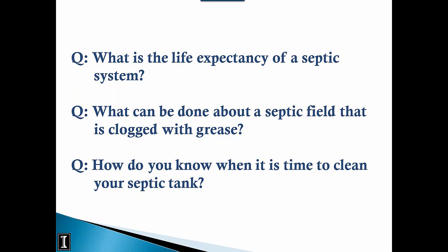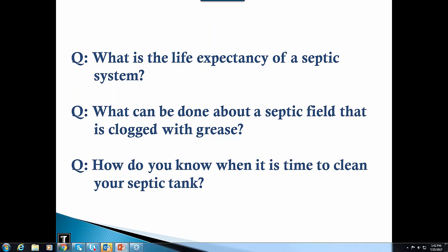And to prevent future instances of grease other than just the pumping, you may consider putting what's called a T-filter on the effluent and the flowing out end of your septic tank. So a little piece of plastic inserts right into the T that leaves the septic tank. The one thing about that is that then it has to be maintained, or that can clog and cause a backup. But it will pick up any solids and any extra grease particles before it makes it into your distribution box and/or your septic leach field.